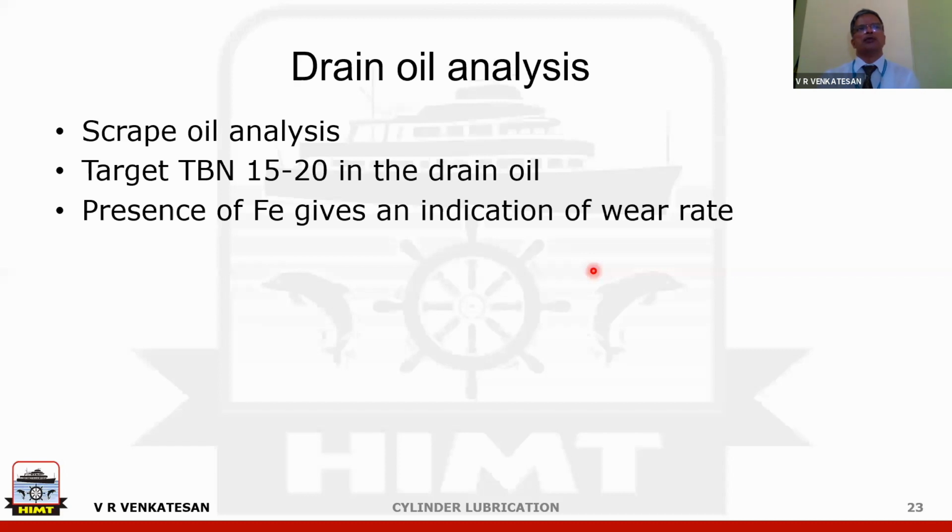In spite of all these difficulties, you can imagine that from the time you fit a piston ring till you renew it, nowadays piston ring renewal is done in many engines after about 24,000 hours. So this piston ring is able to last 24,000 hours.